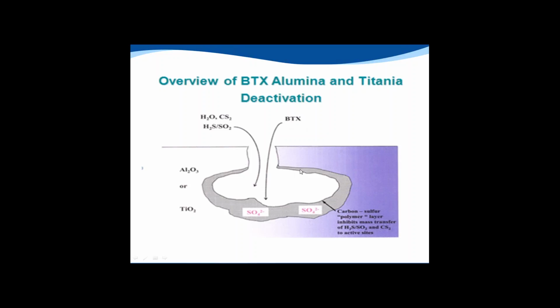We see also with free oxygen a sulfation layer around the catalyst bead that could impact the ability of our reactants to get inside to the internal surface area for the reaction to take place. BTEX and methanol poisoning are a form of permanent catalyst deactivation. Sulfation is reversible. Sulfation is generated by excess oxygen that is present in our converter beds.